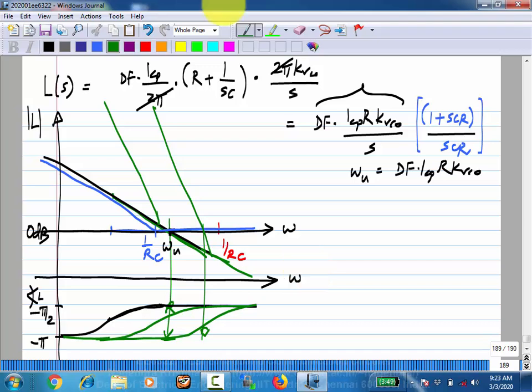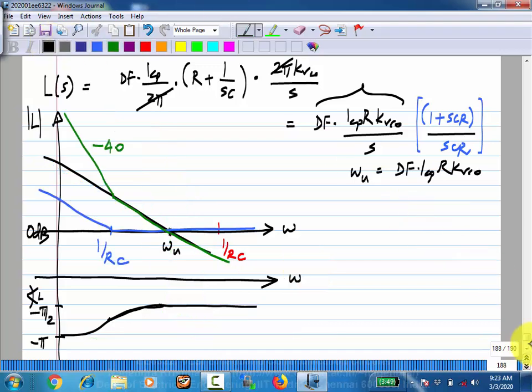Okay. So the zero frequency omega z is 1 by RC and it must be sufficiently below omega u. How much below it is, that depends on other things. Okay. So it will be stable, but it may have peaking and other things that we will look at. Is this okay? What is the significance of this omega u? Unity loop gain frequency. What does it signify?